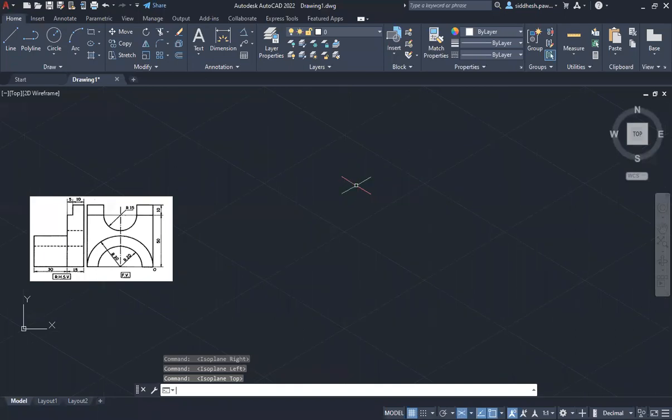Everyone, I'm pressing just F5. It is creating the isoplanes on the right, on the left, on the top, on the right, on the left, on the top. Are you getting it? Right now it is right. So everyone, is it clear till here? Should I move further?